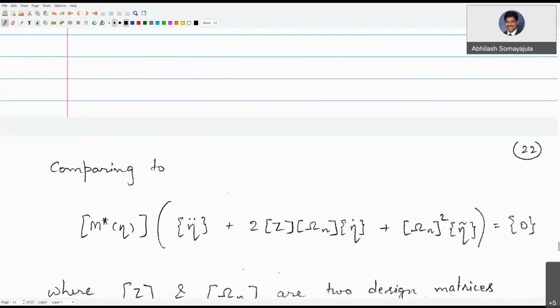Sir? Yes. Then how is this nonlinear PID applied in those aircraft dynamics? Oh yeah, if you want to apply it to aircraft dynamics, you have to include the fact that J is not constant. J is varying with time. And then you have to design your control law accordingly. But the Kp in that case will also... Correct. So Kp will be time varying in that case.